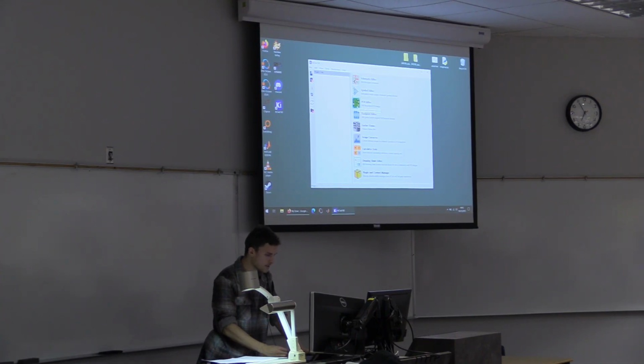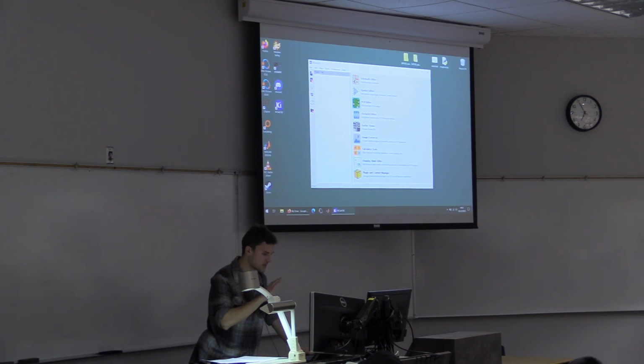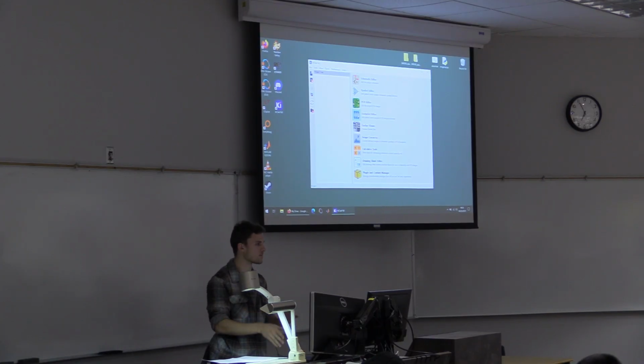You've got your PCB editor, so that's where you would take your schematic, all the parts, all the connections, and then translate it over to a PCB layout with all the traces and vias and holes and all that. And alongside the PCB editor, you'll have footprints, kind of like symbols to a schematic. A footprint is the physical way the part is set on your circuit board. So surface mount components will have two rectangular metal pads usually that you'd solder your component to.